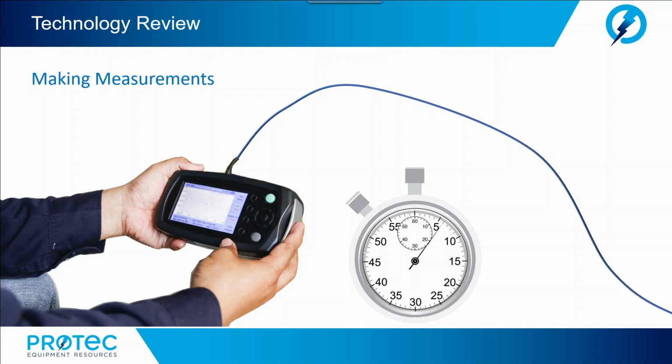If it knows how long the pulse has been gone and how long it has been traveling, it can determine distance. TDRs are like an arithmetic word problem that asks, if you leave Dallas and travel for 2.5 hours at 50 miles per hour, how far have you gone? Because the TDR knows how long the pulses have been gone, if we could tell it how fast these pulses and the reflections travel along the cable, it would be able to calculate the distance from the TDR to the impedance changes. And we can do this.